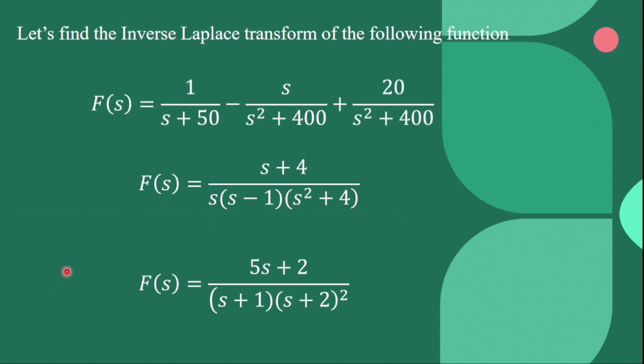And next we take some difficult examples. Here you can see this one is just giving the partial fraction, but the second case is the normal case, just a transfer function. In MATLAB you don't have to convert to the partial fraction, you just write this function and use the command ilaplace. And the third one is the same. In the next video, the third video, we use the MATLAB command to perform the partial fraction. Okay, so these are the answers.